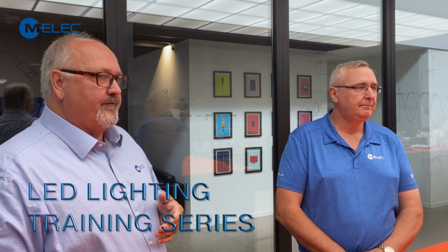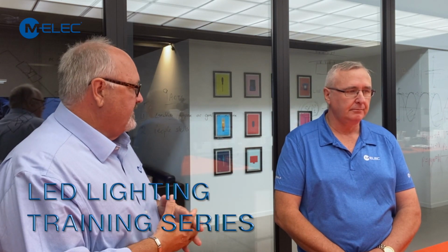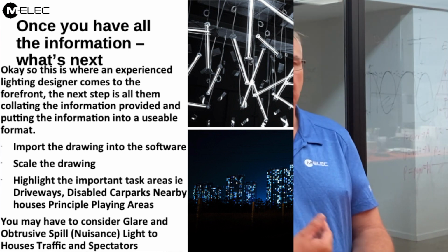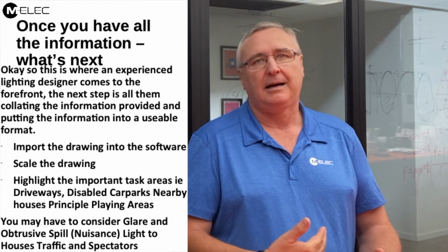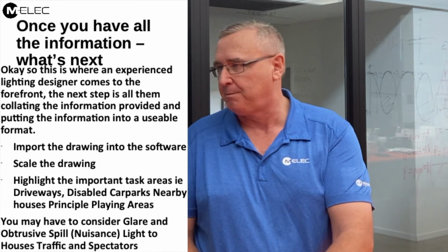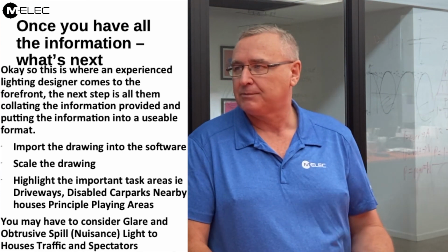So once I've given you my information, is there a solid process behind the scenes that you take? Absolutely. Once I've got all the information for the drawing, I'll import that into the lighting program, whether it be a PDF or an AutoCAD, or if I've got to draw it manually into the lighting program. Once I've done that, I'll set up my calculation planes. I'll also put a line where the boundary is that's been noted, and I'll put a calculation plane on the boundary as well. And then I'll choose a luminaire based on what I think is the best luminaire for that job. And then I'll do all my calculations.